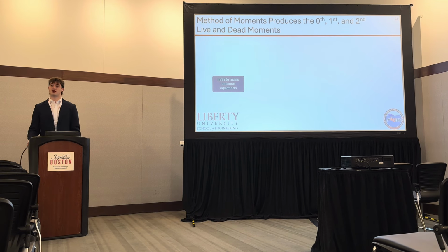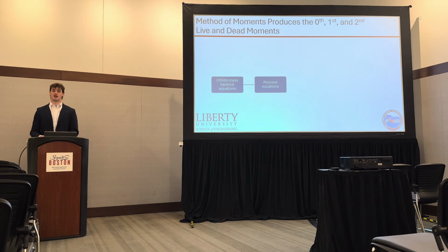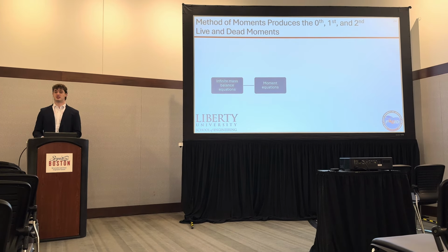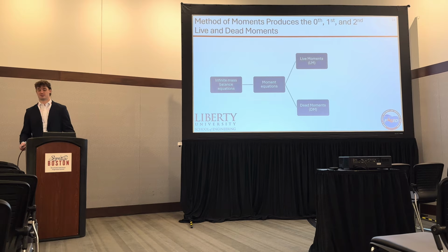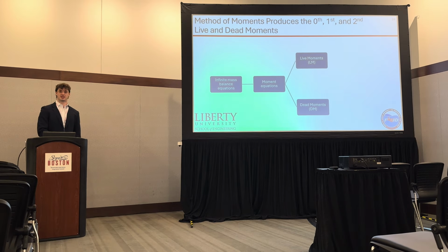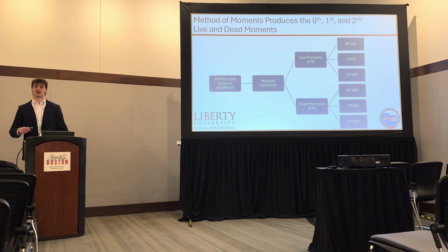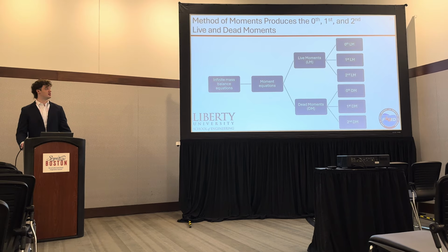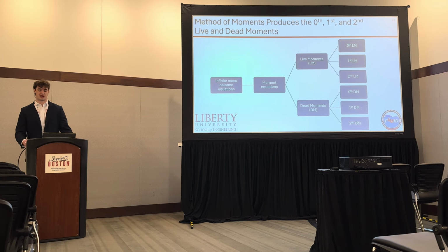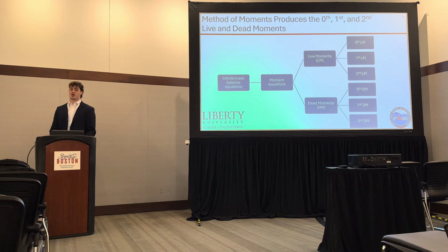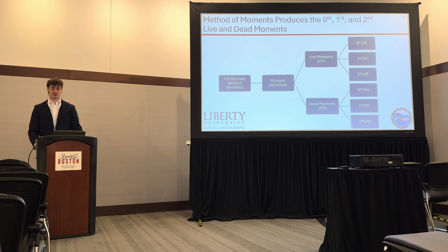So a little bit more into the method of moments. As I said, you take that infinite amount of mass balancing equations and convert it to a finite set of moment equations, but those moment equations are made up of live moments and dead moments, and the live and dead moments are made up of 0th, first, and second moments. Now, live moments are crucial for capturing information about ongoing reactions, while the dead moments are for characterizing the population that has already completed the reaction pathways.